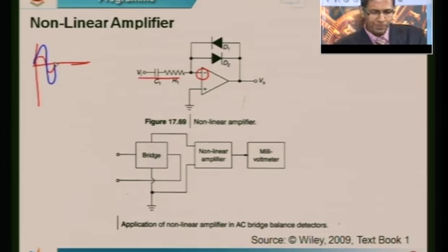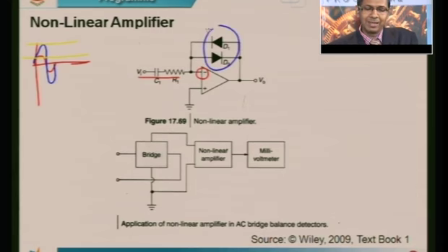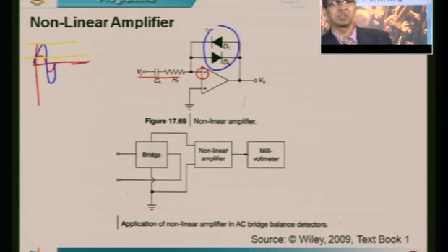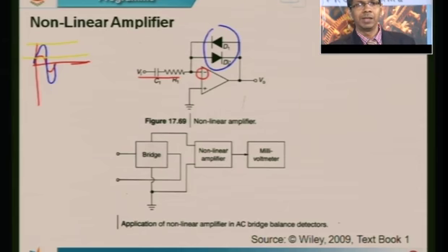How is it possible? It is possible if you look at their amplitudes. The red one has a smaller amplitude, whereas the blue one has a larger amplitude. For the time being, let us ignore the diode part of it, right? Let us say my signal is very small. If my signal is very small, it can neither forward bias D2 nor forward bias D1.